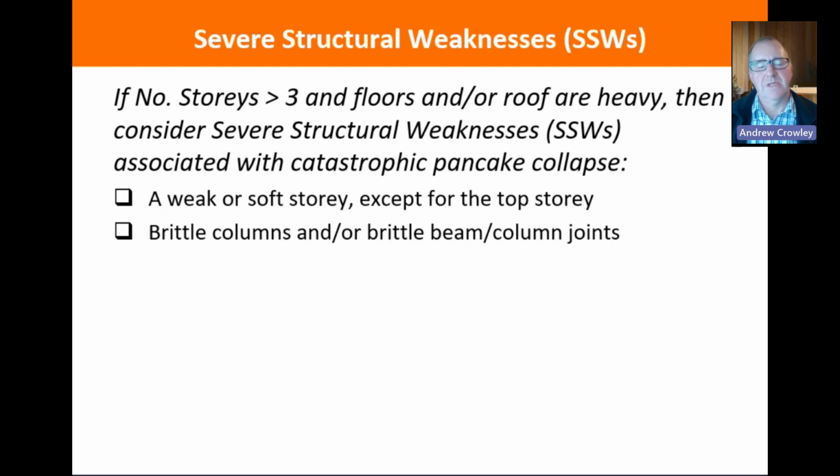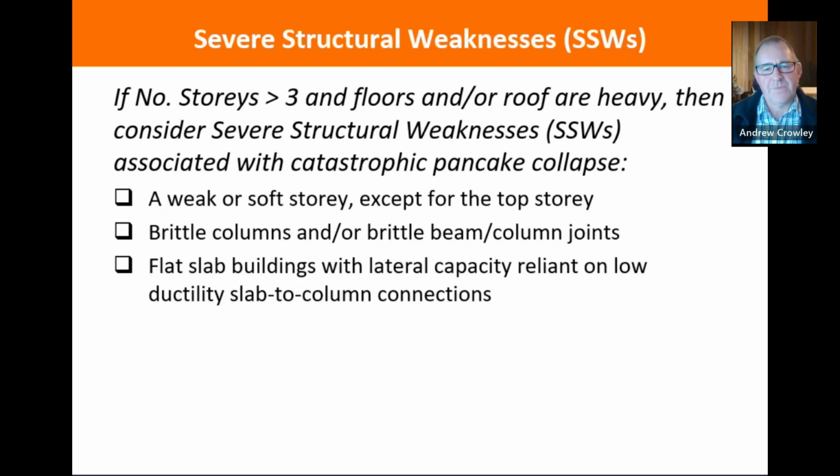And that may be revealed by the drawings. If you've got, for example, reinforced concrete, you'll see where the containment steel is or isn't, and see whether the reinforcement is continuous or not, and whether the lap lengths are adequate. Is it a building with a flat slab? And if so, is that flat slab reliant on the low ductility of the slab column connections?